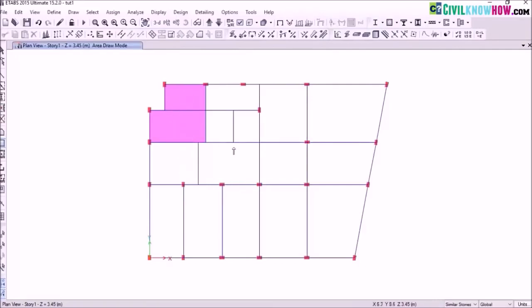but there is an alternate method which is much more effective actually, and you can save a lot of time too. That is, I'm going to select the slab from here to here. So over these 3 sections actually I have assigned a single slab. By adopting this method, I can save a lot of time. That is, I'm going to select the slab and the frames. So I need to split my slabs between these 2 frames.